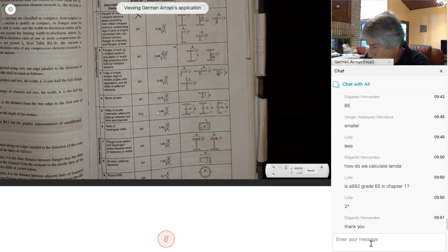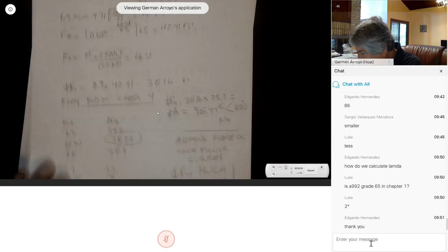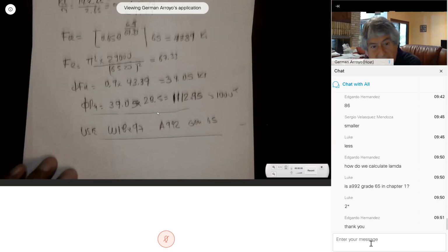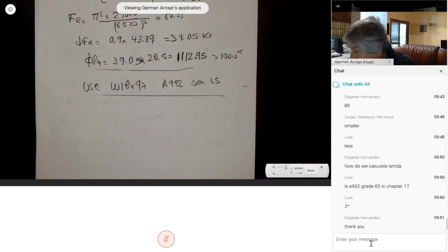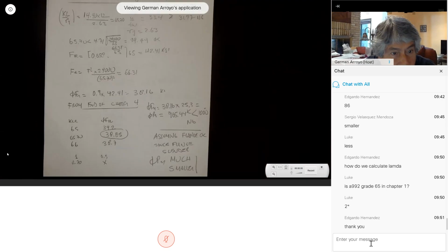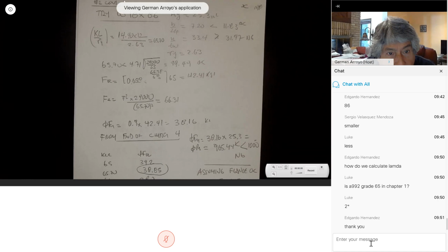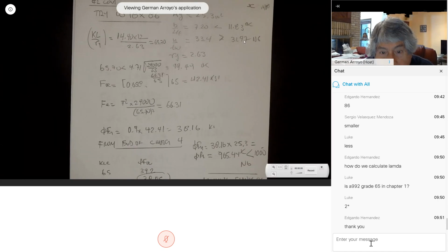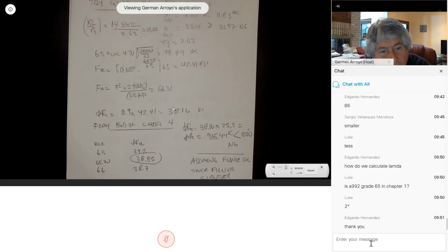So the point that I wanted to make in here is that when I check the next section, the W18 by 86, when I checked this section, we knew that we had a problem with the web. I ignored it. I assumed that there was no problem. I did the computation the same way that we always do.